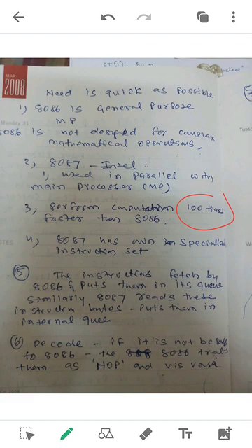The 8086 is connected with the 8087 in parallel. So the fetch and decode are performed in parallel, and the instructions are stored in a queue. Already we know what the queue is. So all the instructions are stored in a queue. The instructions of the 8086 and the instructions of the 8087 are both present in the queue.